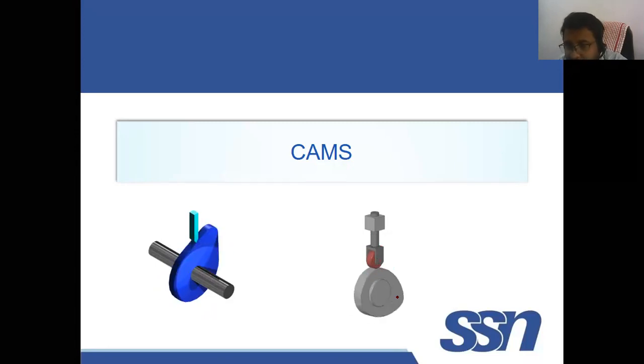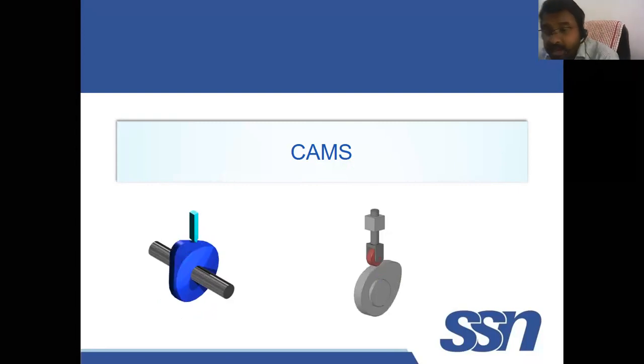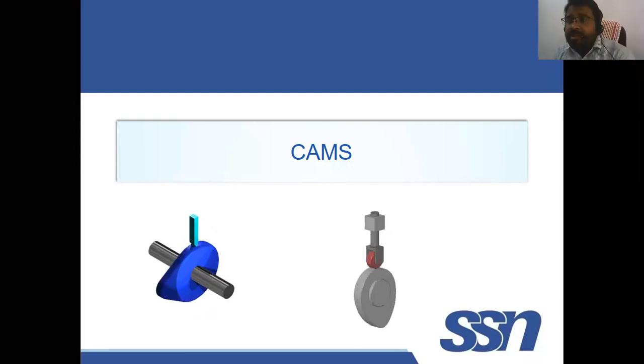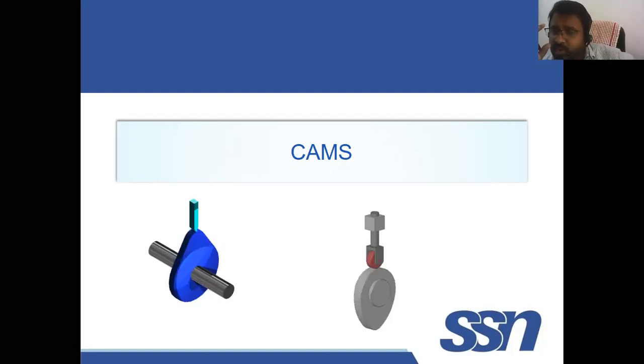So the cam is designed such that it can make the actuation only at that particular time interval, and at that time it should give an upward motion. Based on how many RPM it rotates and at what time it should give the lift, it is given as input. It is designed so that it will give the lift only during that particular theta, and the fashion in which it gives uplift and downlift is the desired kinematic motion.